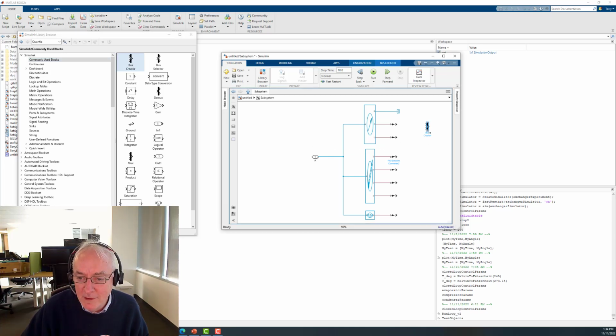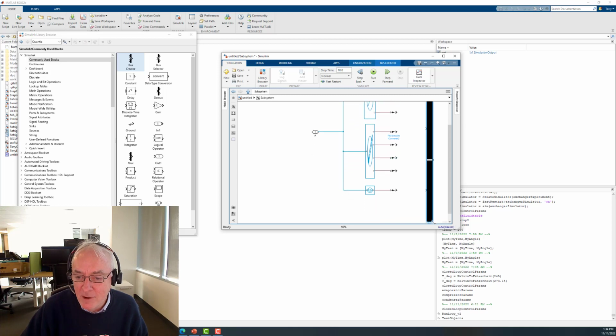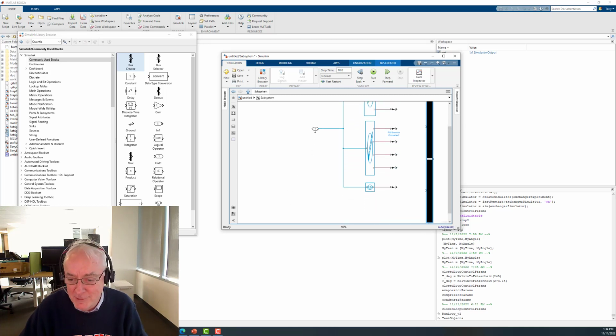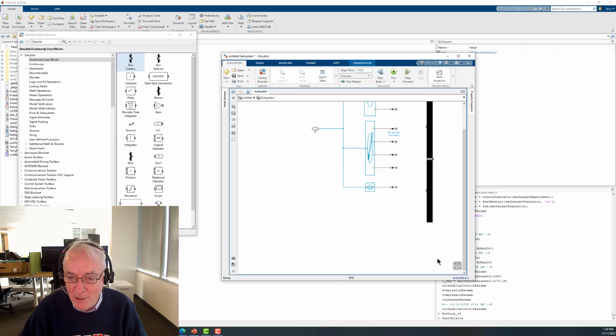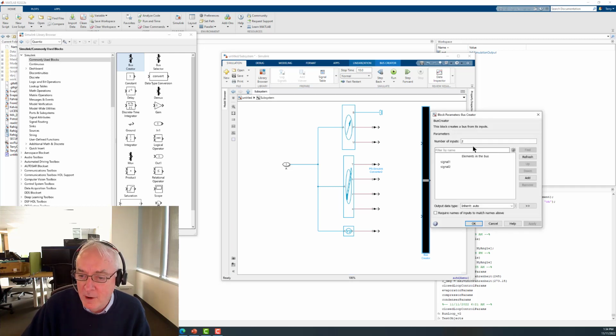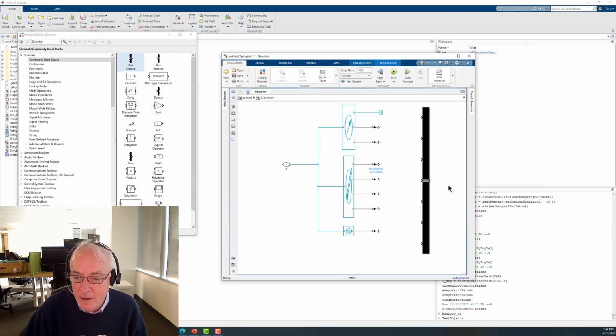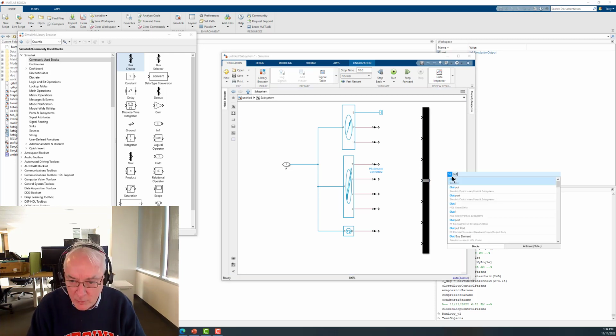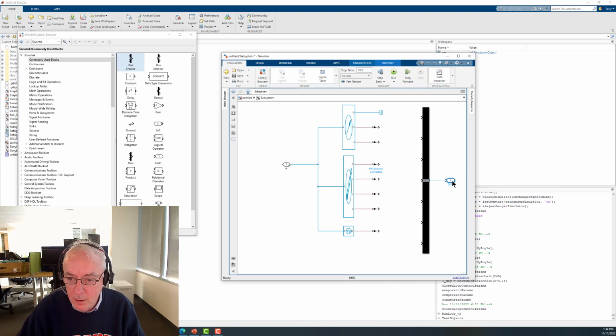Why would you do this in Simulink? Well, it's because Simulink is loaded with all kinds of great stuff. That's the short answer. And we'll probably see that a number of times, but here's a specific example, and that's the use of these buses, right? And so let's go ahead and configure this. It's going to have 7 entries, and with that, we'll have a single output port, and I'll simply call this M bus, M for measurement, okay?